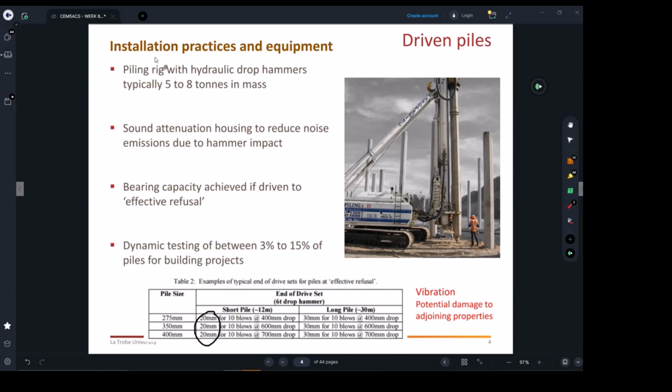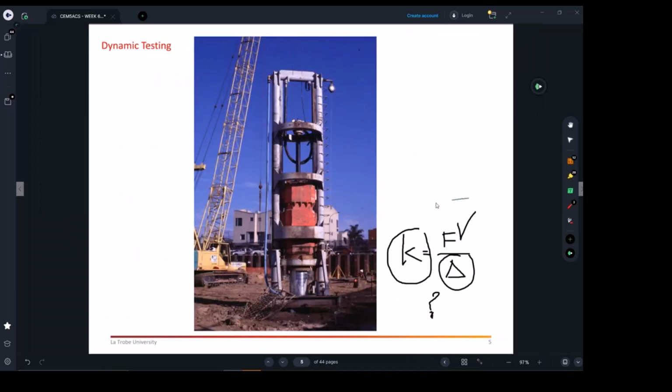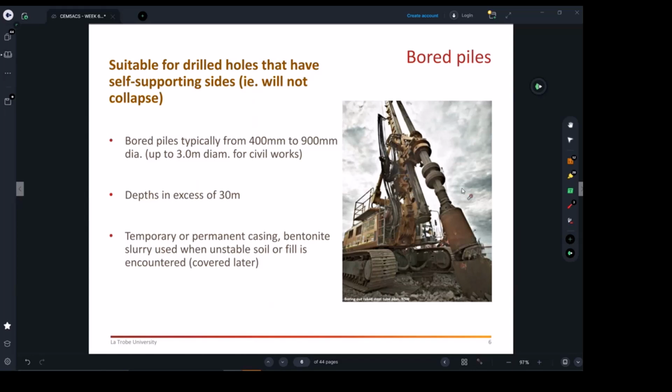And basically you need to understand the reasons behind why we use piling, what issues we can have from piling systems, for example, the sound and vibrations, and how the piles resist load, which we said is by the bearing at the bottom, and also the side friction as well, right? You won't be asked about these equations. You just need to know the construction intent and what's really happening there.